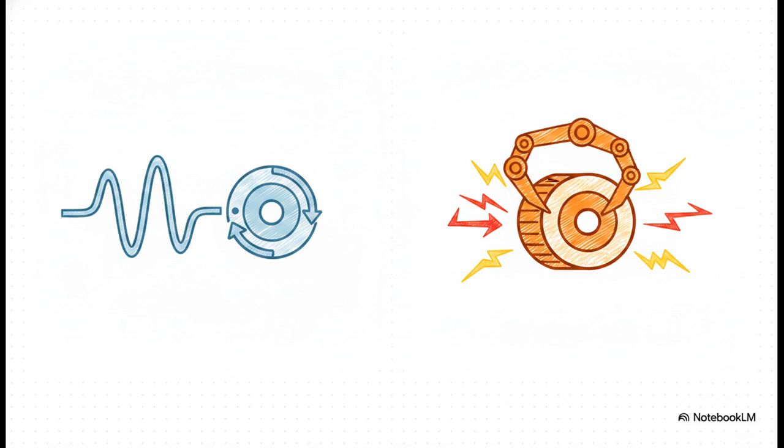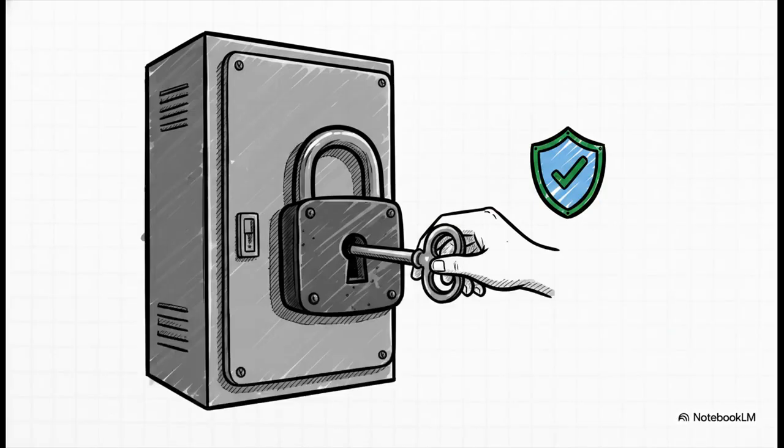But if you set it to 1, you enable vector control. This mode actually modifies that mechanical characteristic curve, making it absolutely ideal for more advanced applications where you need really tight torque control. But hey, before we leave the lobby, you've got to lock the front door. Parameters 00.08 and 00.09 are where you enter and verify a password. In an industrial environment, preventing unauthorized tampering is just as important as getting the motor spinning in the first place.